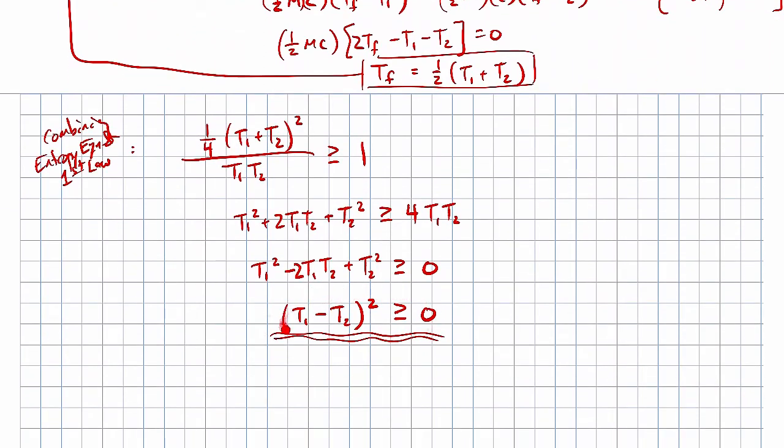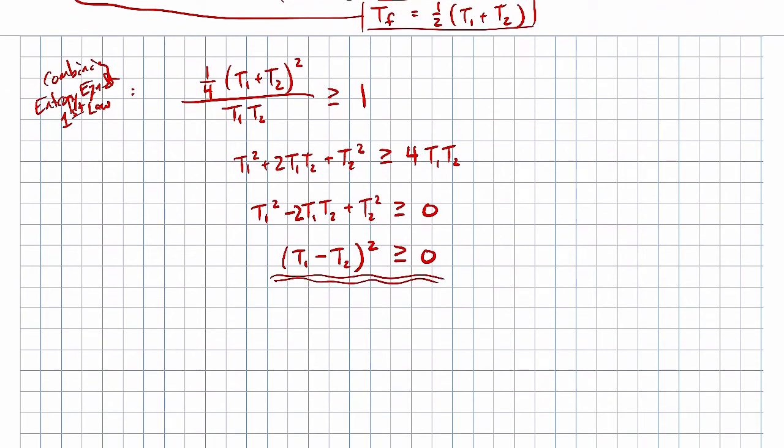So this expression is what we must have in order for the entropy production to be positive or equal to 0. So you can see right away, if T1 is equal to T2, you'll get sigma equal to 0. The entropy production will be equal to 0. And this is our internally reversible situation. Basically, since it's the same liquid, you remove the partition, nothing really happens. The temperature doesn't change. You just have the same liquid just sitting there. So nothing's really happened there.